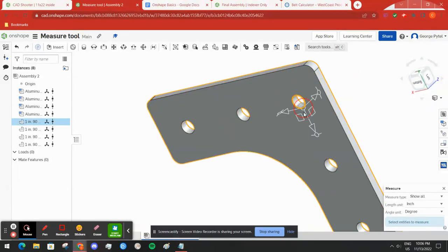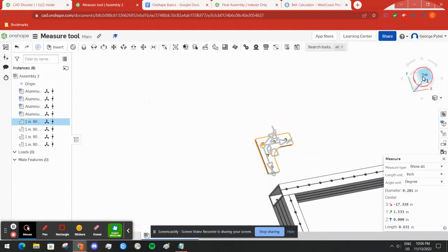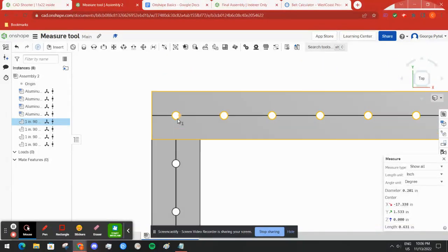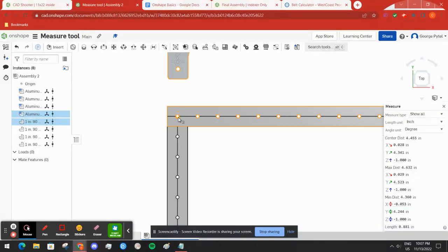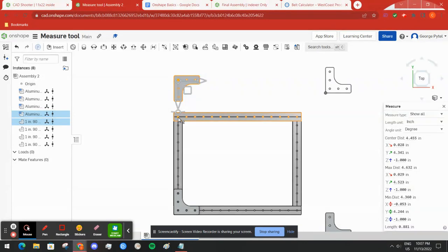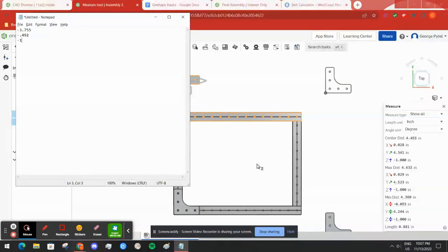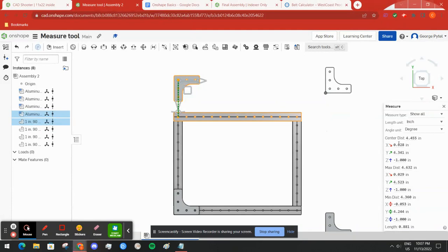As you figure out, this can be very time consuming, and especially if you're dealing with multiple gussets, such as in Indexer, or if you're mounting even bigger parts of VersaFrame or entire different build teams into the robot, like if you mount the shooter onto the Indexer or the pickup onto the Indexer. So again, we're going to use the center distance.